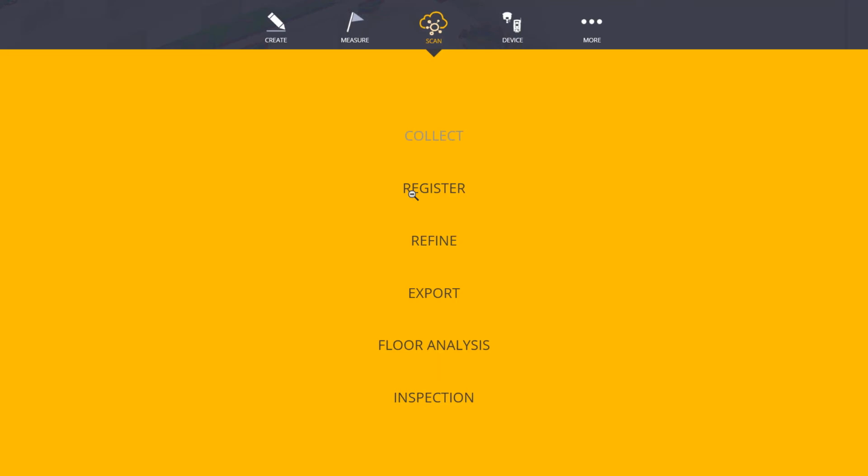It's going to look at the geometries of walls, doors, floors, ceilings, and use those planar surfaces from scan 1 to scan 2 to scan 3 and say, oh, I see that geometry in these 3 scans, therefore they must fit. And typically we want at least 30% overlap to get the best geometry fit. So hopefully that helped.